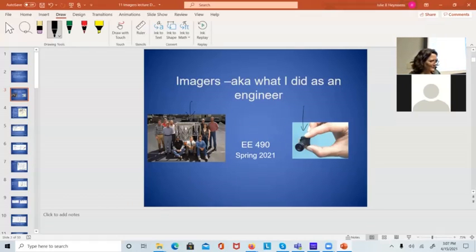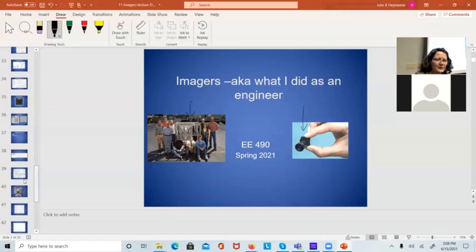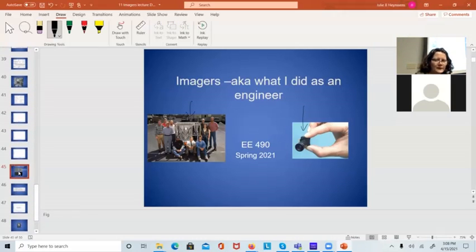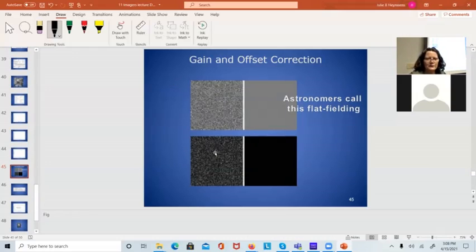I know back when we were doing the DRAM puff, Jack and I were looking at making a CMOS imager puff out of the, we'll get to that later. I got pictures of it in here, but we can talk about it a little bit now. So right here, if I read an array in the dark, there's a lot of noise pixel to pixel. And this is because every diode is a little bit different size. It has slightly different dark current. This is the amount of electrons that are just decaying out of that p-n junction depletion width all on their own.